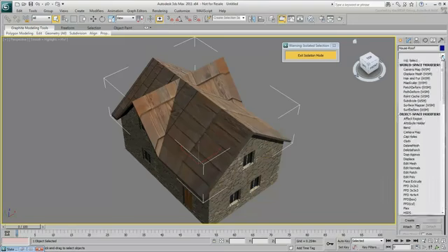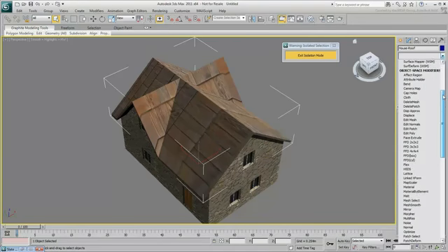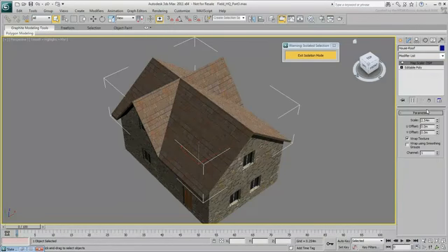To make the shingles conform to the slopes of the gables, you can use the Map Scaler modifier. Make sure you choose Map Scaler in the Object Space Modifier (OSM) list, which applies locally to the object. The Map Scaler modifier maintains the map scale relative to the roof and wraps the texture so that the shingles follow the angles of the roof. Not all game engines recognize the Map Scaler modifier, but you can collapse the stack to bake the mapping coordinates